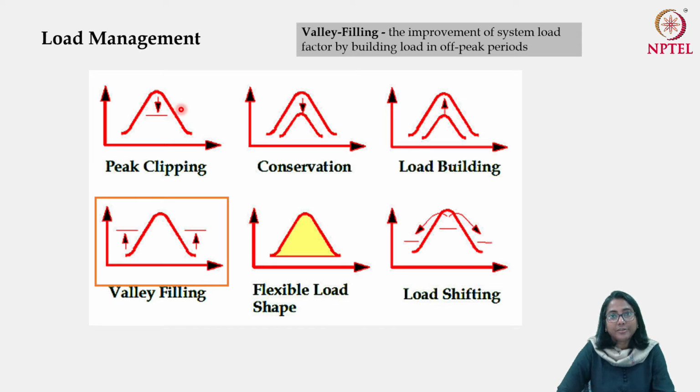The second one is valley filling. Why is valley filling important? Now again we have an understanding. If we can fill up the valley, then the part of the power plant which remains underutilized, the capacity which remains underutilized, will come down. Therefore, it's important to have valley filling activity in order to increase the efficiency of the whole investment system. How can the valley be filled? So some activities can be undertaken at night or during the periods when you have very low electricity consumption.